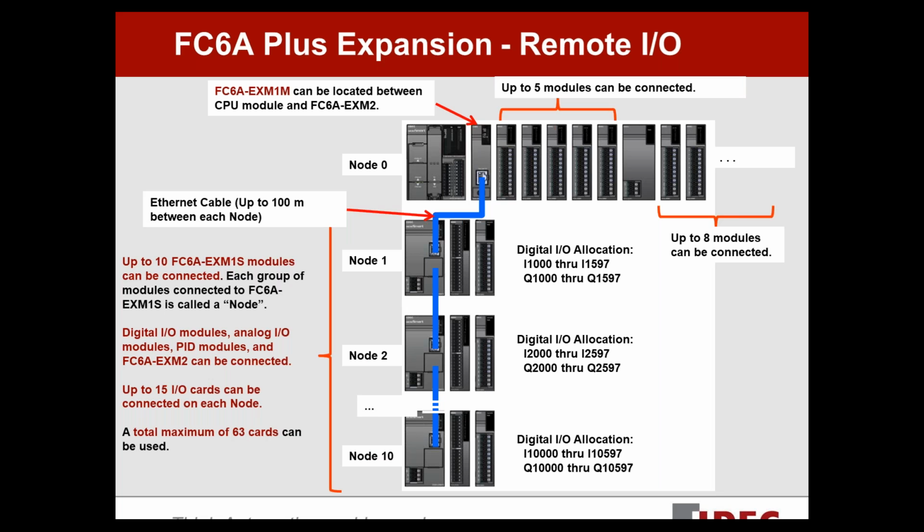But that thing has an Ethernet port. So after I plug that in, then I can connect up to 5 I/O cards. Then I need to connect an expansion power supply if I need any more I/O cards after that. So again, if I'm using a master remote I/O module, I can have up to 5 cards after it. Then I need to use an expansion power supply if I need additional I/O cards. And again, I can use up to 8 after that expansion power supply.